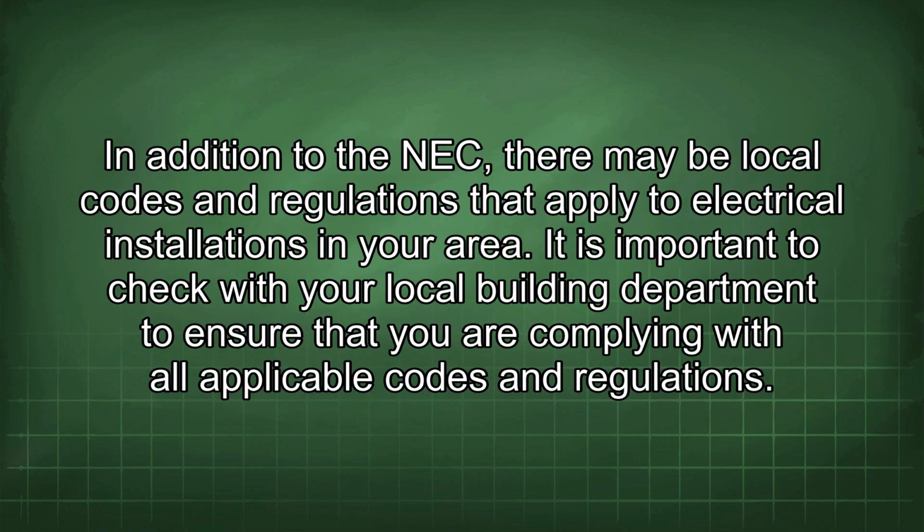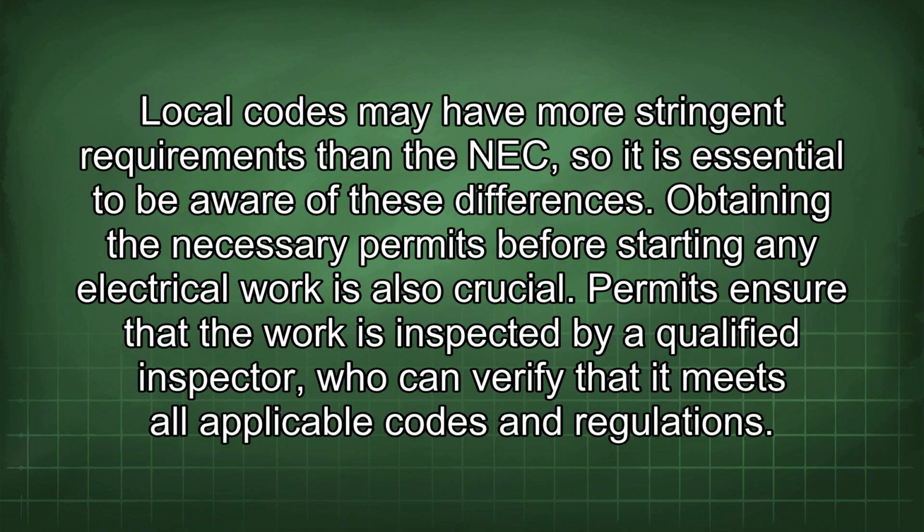In addition to the NEC, there may be local codes and regulations that apply to electrical installations in your area. It is important to check with your local building department to ensure that you are complying with all applicable codes and regulations. Local codes may have more stringent requirements than the NEC, so it is essential to be aware of these differences. Obtaining the necessary permits before starting any electrical work is also crucial.